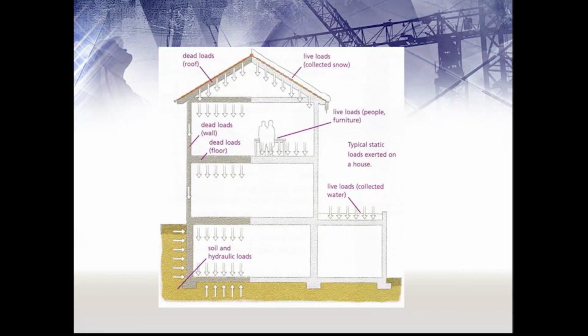During the design, we have the dead load here. We have partitions, equipment and people. We also have the partition wall as part of the dead load, as I was mentioning, and then the furniture on the ceiling. There can be the lights, the pump and all the equipment for plumbing that we include in the ceiling.